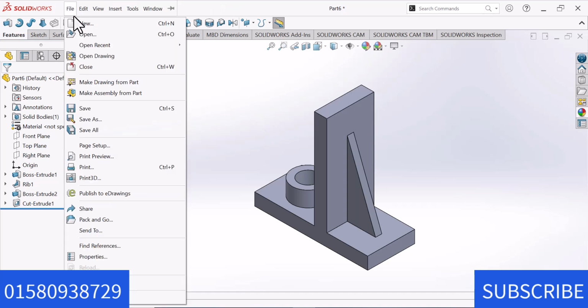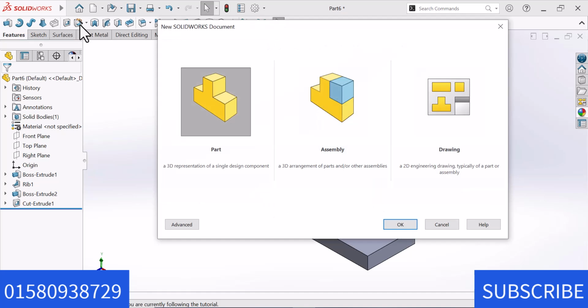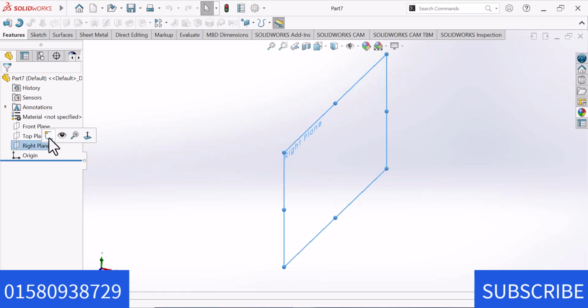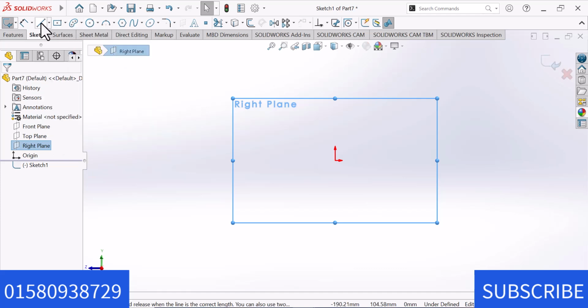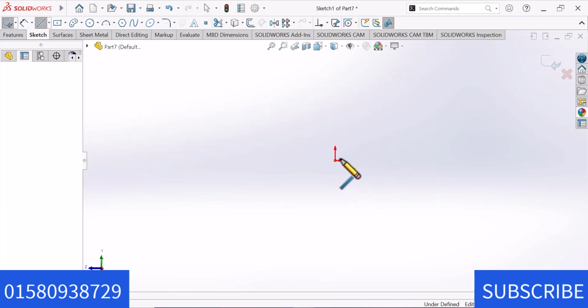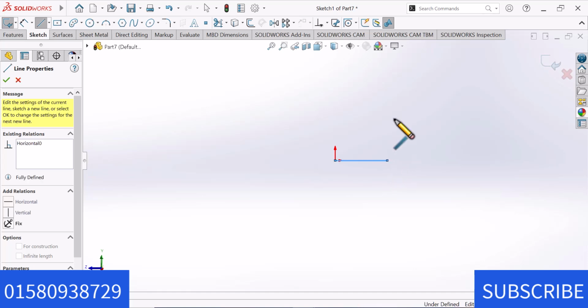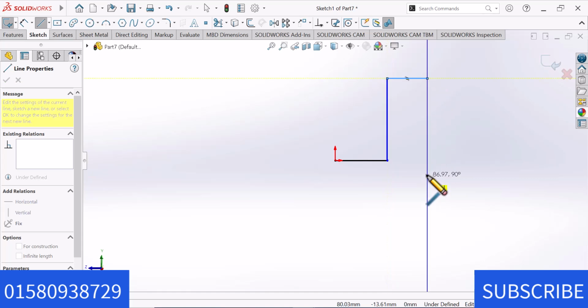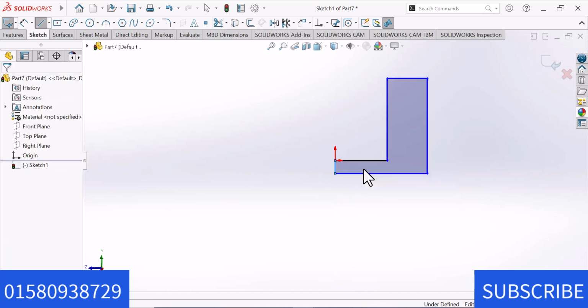Now I am going to again select New, Part, and select OK. Now I am going to select right plane and sketch. Now draw the line from origin, horizontal and vertical, horizontal, vertical, and horizontal and vertical. Select. Now go to dimension.